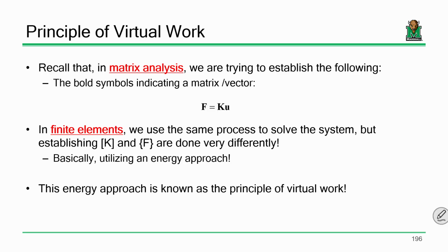That's fine if you're dealing with members that are simple. Bars, beams, trusses, things like that. It's easy. That's simple. When you're dealing with a 3D model of a V8 engine and you're doing thermal and mechanical stress analysis in the nonlinear range and you're using tetrahedral elements and brick elements, direct stiffness doesn't work, okay?